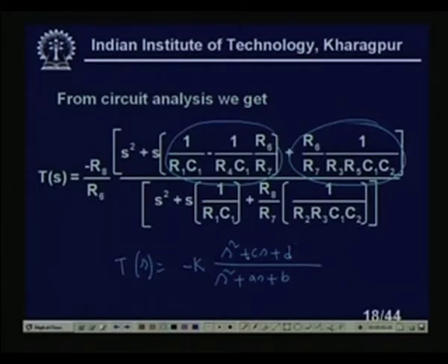Suppose in this case if I make C 0 and D 0, it will be a high pass structure, right. Similarly, if I make R6 infinite, in that case I can make this a low pass or band pass structure, like that it goes, right. So, with this type of structure obviously I can generate any filter function.